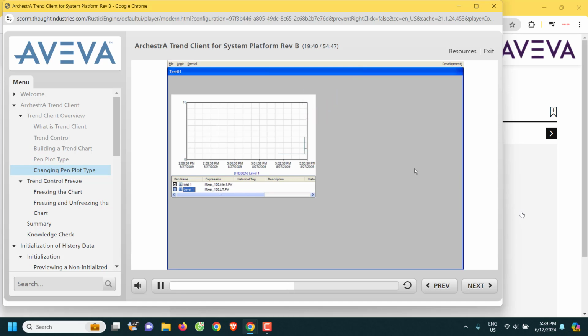valve state changes. We now see a very different plotting on the trend. When the level reaches 0, we can see that the valve changes states. The valve opens. Now we see that there is a transition to a traveling state, then drops down. To finally the level at about 60%, we can see it close. Now we see a step line versus a straight line. This makes a lot more sense for this particular value. We see open, travel, fill, and close.